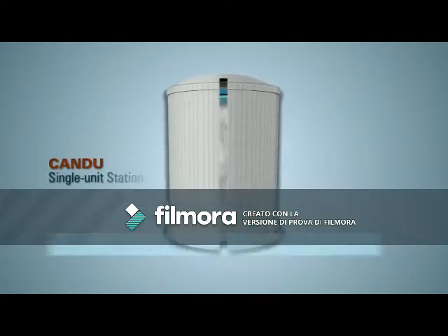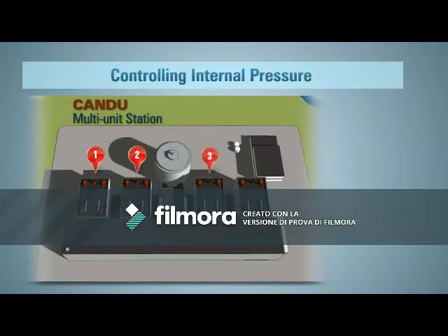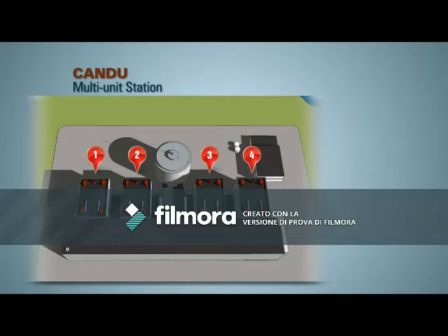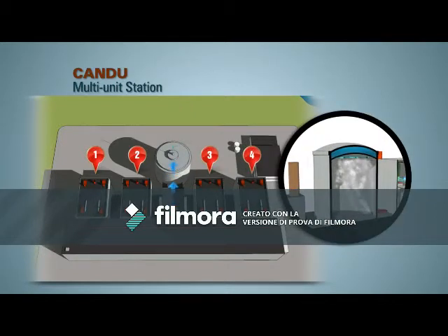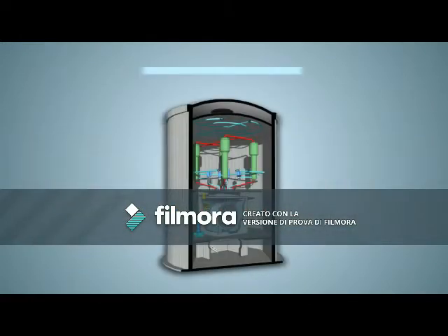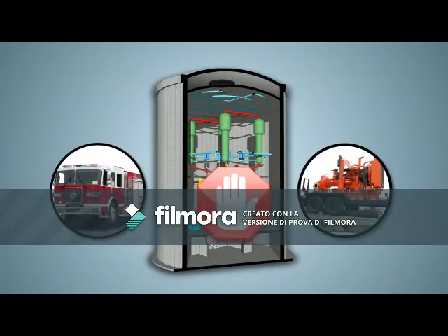At this point, internal pressure inside the reactor building must be lowered. In a single unit station, internal pressure is lowered by spraying water from the dowsing tank. In a multi-unit station, pressure is lowered by releasing steam and hot gases from the reactor building to the vacuum building. The vacuum building is a structure specifically designed to quickly and safely lower pressure inside the reactor buildings. Both systems work without power. Again, supplying water to the calandria using emergency equipment such as fire trucks would stop the accident.